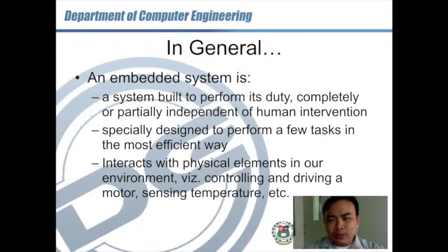For example, a digital thermometer is very popular right now. If you read the temperature, you are seeing a 7-segment display or an LCD. So it's an embedded computer reconstructing the data from the analog-to-digital converter so that we can read the temperature as digits, not bits.